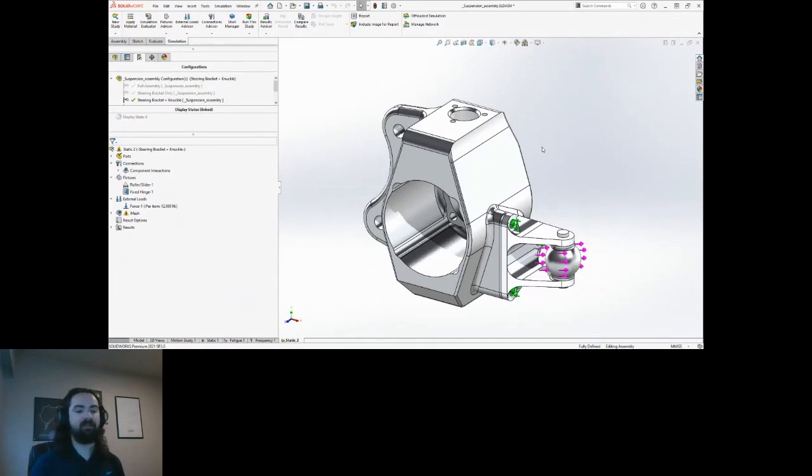Now, in the first simulation setup, I simplified the study by assuming that the bracket is rigidly flat against the knuckle, and that the 3 bolts were rigid without any preload, allowing me to use a slider fixture on the flat faces and a hinge fixture on the cylindrical faces, while leaving the knuckle and bolts out of the simulation altogether.